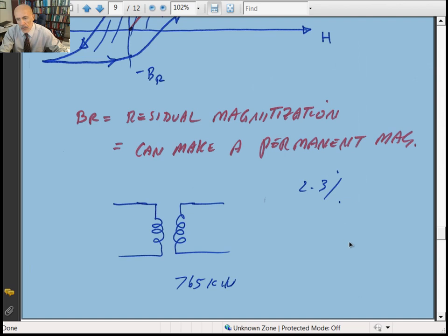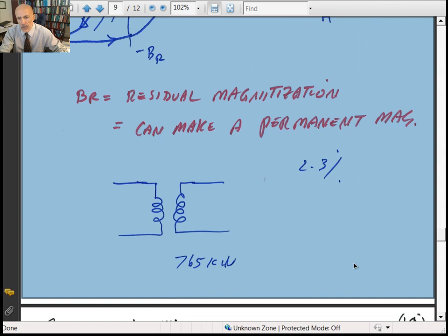And then when they get to the residential or distribution area, they drop it down to 34,000 volts, and then eventually to 208 volts or 120 volts, depending on single phase or three phase, or line to line or line to neutral voltages.